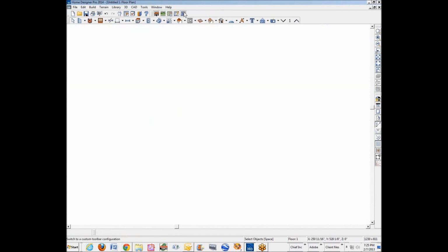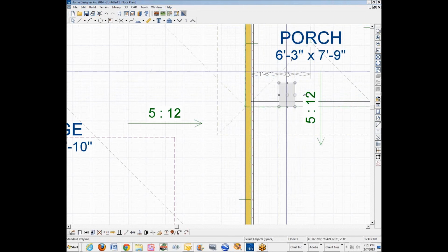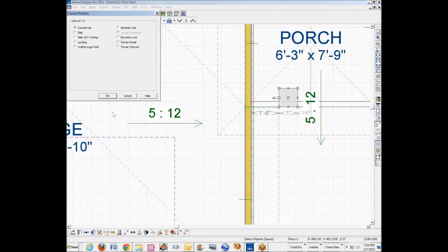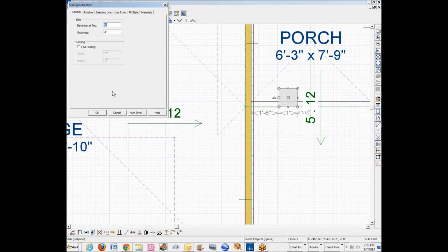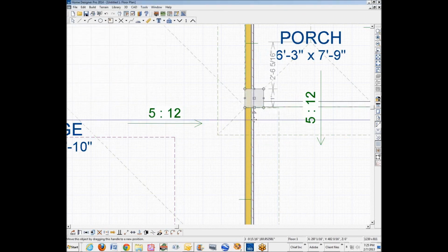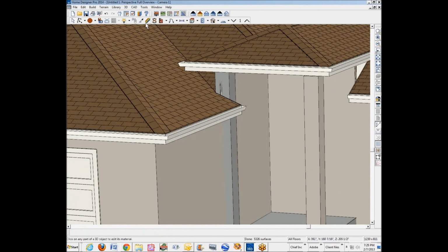I'm going to go to the CAD tools using this toolbar here, draw a figure, make it 12 by 12 like the other one, 12 and 12. And then use a convert tool right here, convert polyline into a slab. Now I think that column is 12 feet tall, and I want it about 13 feet thick. The top of it's going to be near 12, and then it's going to extrude down from that. I'm just going to leave it like that. Okay. That's kind of sort of what I wanted.